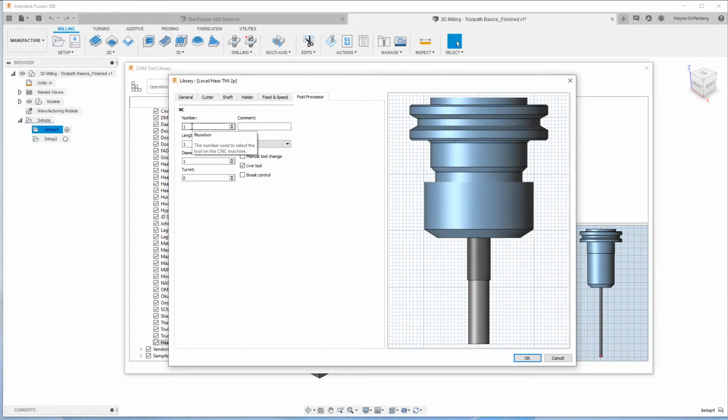This number is our tool number. The length offset is in your table. According to tool number 1, this will be the length offset that you would call in the table for tool number 1. Same thing for your diameter offset. Often in the machines I ran, we've always kept this the same, but that's not the rule. You can always make a specific length offset for a specific set of tools, and then you can set those up independently. We can also turn on our coolant in here.